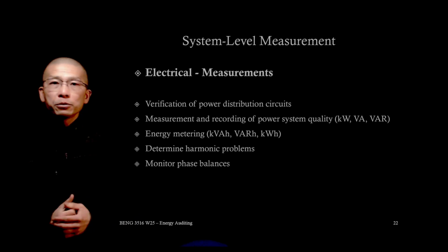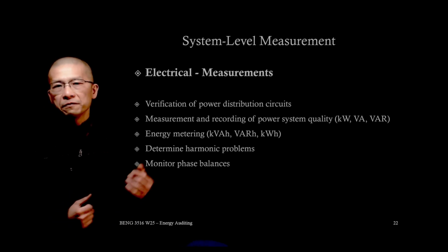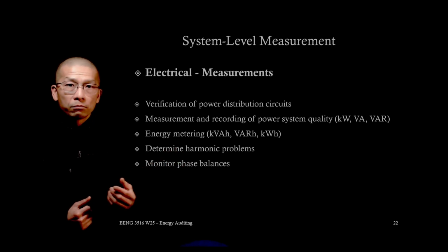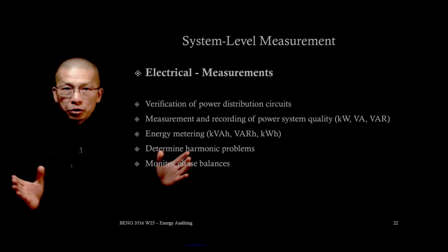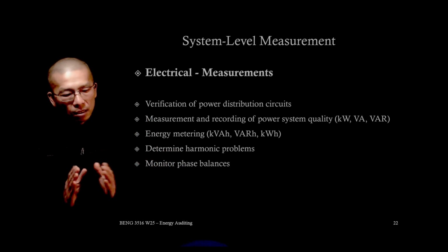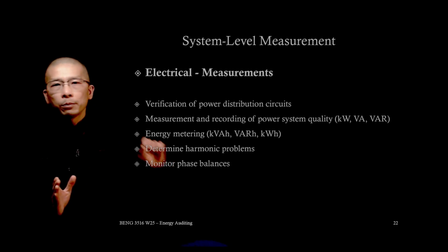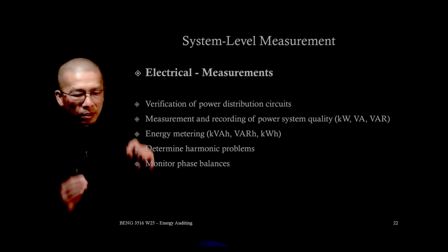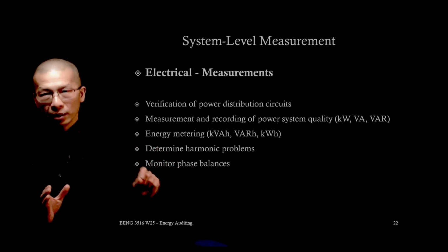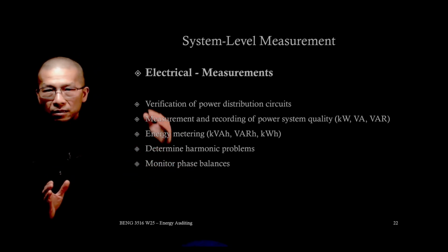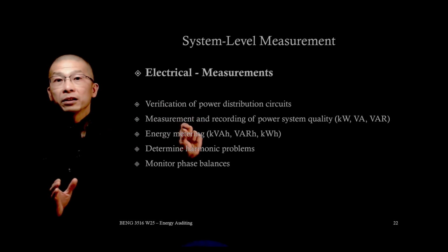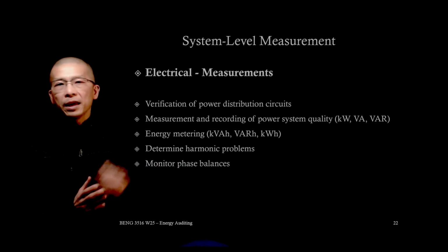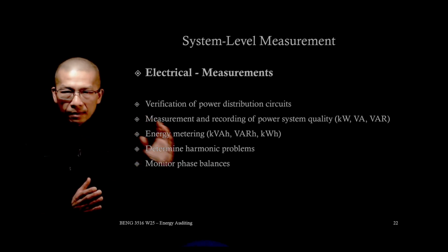For electrical measurement in an energy audit, we first verify the building's power distribution. Always check the distribution circuit: are they properly connected, or is the wire properly rated? You cannot use too small of a wire for something where a larger wire is required. Okay, and then measure and log